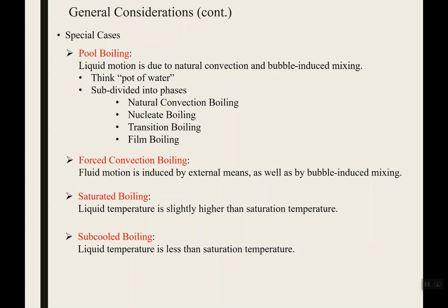There's also forced convection boiling, which is when you have boiling combined with forced convection, just like we saw in the boiler. You'd have those tubes passing through your firebox, and as the water goes through those tubes, heat transfer happens because of the flow of the fluid, and also because of the bubbling and mixing and boiling that happens inside the tubes. There are also some others, saturated boiling and subcooled boiling, which are kind of interesting.